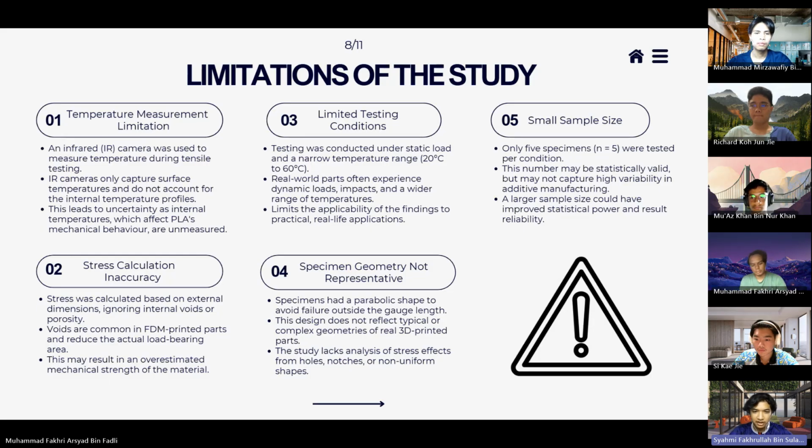Next, specimen geometry is not representative. The specimen in this study had a parabolic shape to avoid failure outside the gauge length. This design does not reflect the typical or complex geometry of real 3D printed parts. The study lacks analysis of stress effects from holes, notches, or non-uniform shapes.